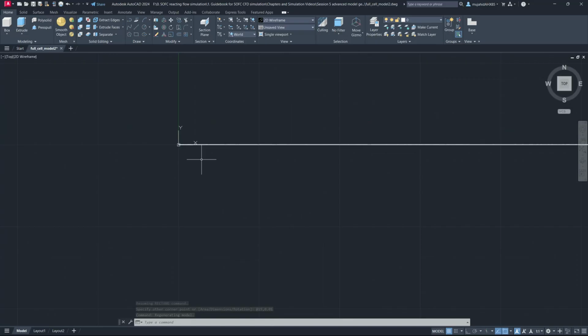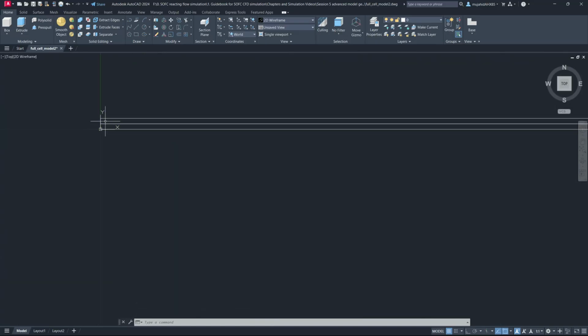So now we have modeled the CFL and CCL, and then we have the mesh. We have the mesh of 0.3 mm on the cathode side, again at the rate of 19, 0.3 mm.